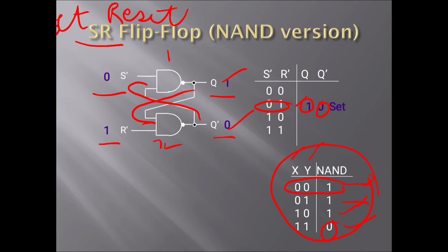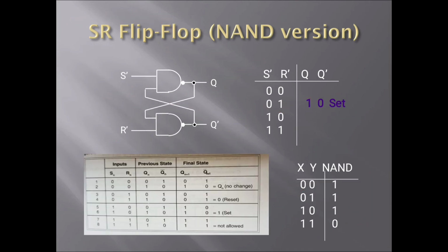So when we get the next clock pulse values 1 and 0, it is the same as the previous values, that is 1 and 0. So it is called the set state. There is no need for a change of values.